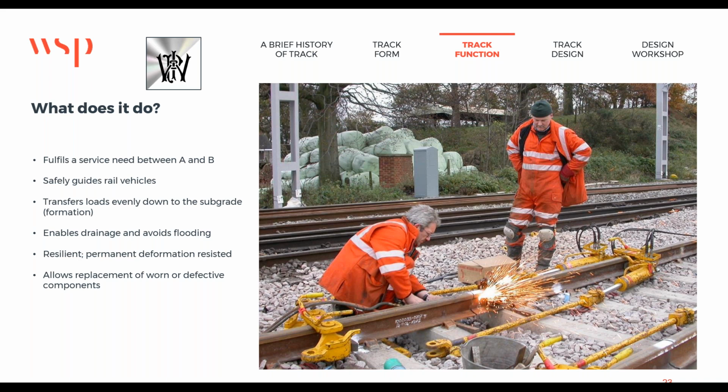Sustainable track form renewal policies can be implemented. Ballast can be screened to remove fines and small particles, and the ballast layer supplemented with new aggregate. What you take out can be cleaned and recycled again, and worn rail from higher speed lines can be removed and cascaded to lines with lower speeds or lower tonnage. We just have to think sustainably about that and realise that it will cost money, but it is actually sustainable.